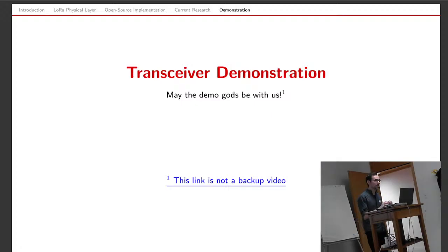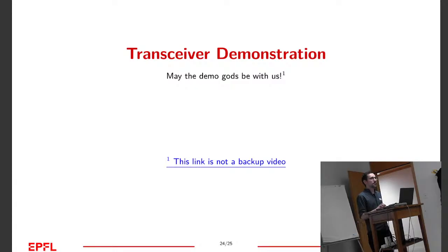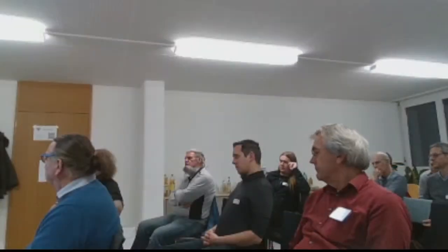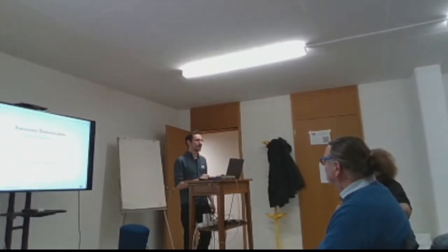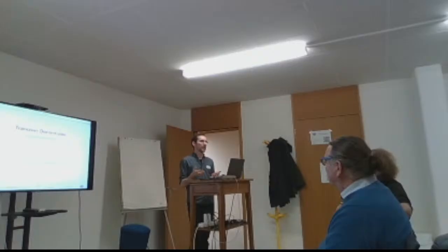After. So the ISM bands, plural. Which ones are they, what are their limits? Is this a European, North American band, or is this something else? If you want to use LoRa, in Europe they use the 868 megahertz, and in the US 915. But there is also some version of LoRa now that uses the 2.4 gigahertz, the same as old Wi-Fi. They just use whatever is free.